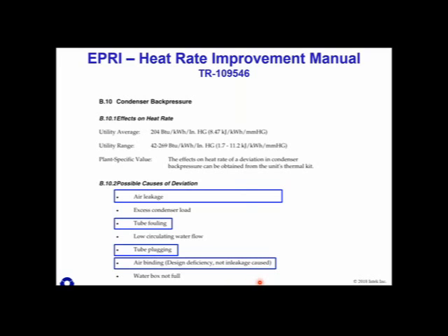And on this list, you'll see some of the usual maintenance-related issues that you're facing that we just talked about: air in-leakage, fouling, things like that. And so, figuring out which one of these is causing the biggest problem quickly and reliably is going to be a focus for these case studies. So, very quickly figuring out, is this an air in-leakage problem or is this a fouling problem, will be a focus.